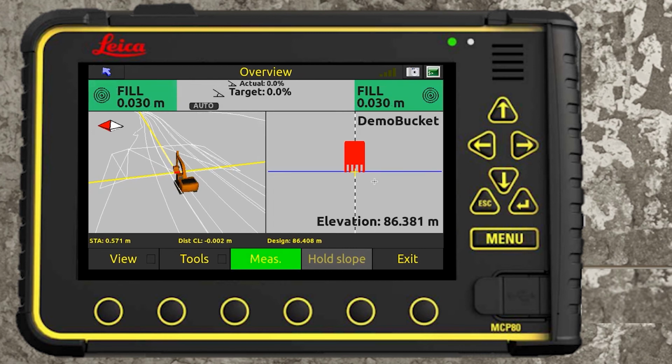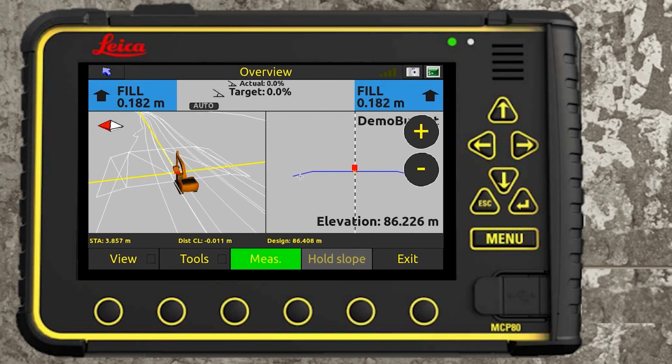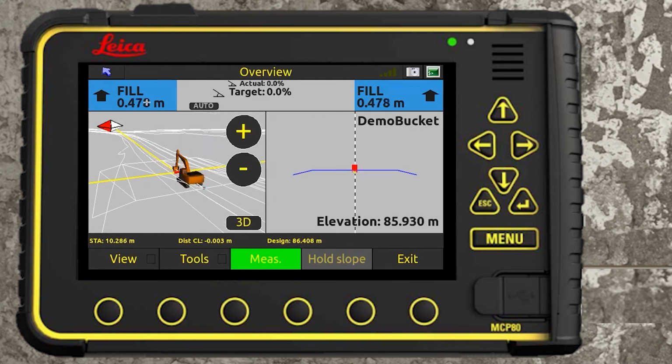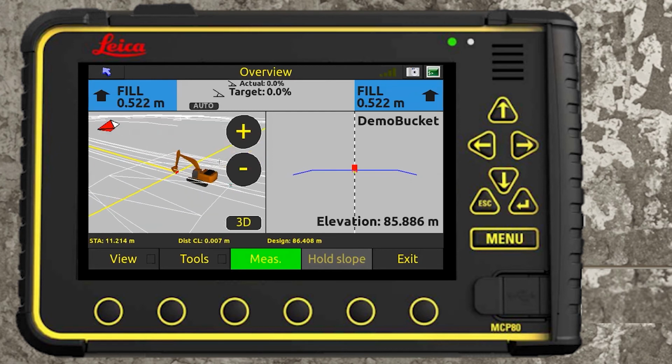Well, there you go. Now if we zoom out, you can see quite clearly those ends running off at my minus 25%. So I have 20 meters across, and then these 5 meter ends at minus 25%. Again, we have that set to 0, so you can see the fill is gradually increasing. It's 20 meters long this time. If we had left in that slope that we took the points off, this would be in around 10 mil, whatever we started off at.